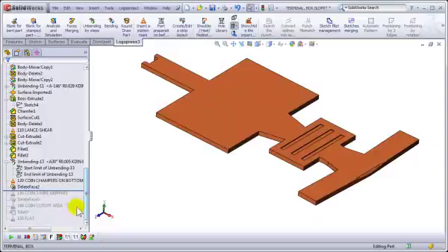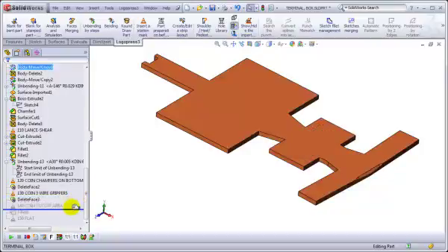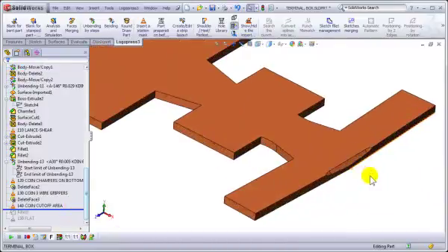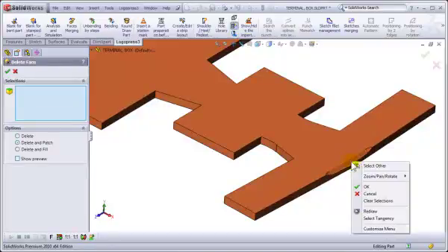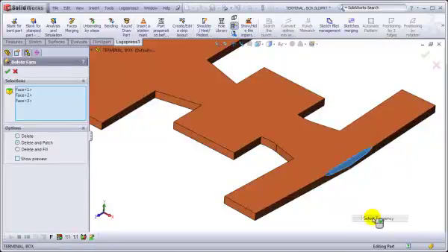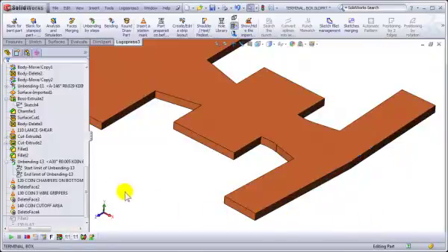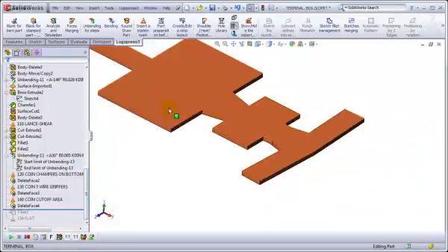Then continue to roll forward, coining the 3 wire grippers, deleting those, and coining the cutoff area. And then before it's coined, it's not, so we use delete face feature again to get rid of that.